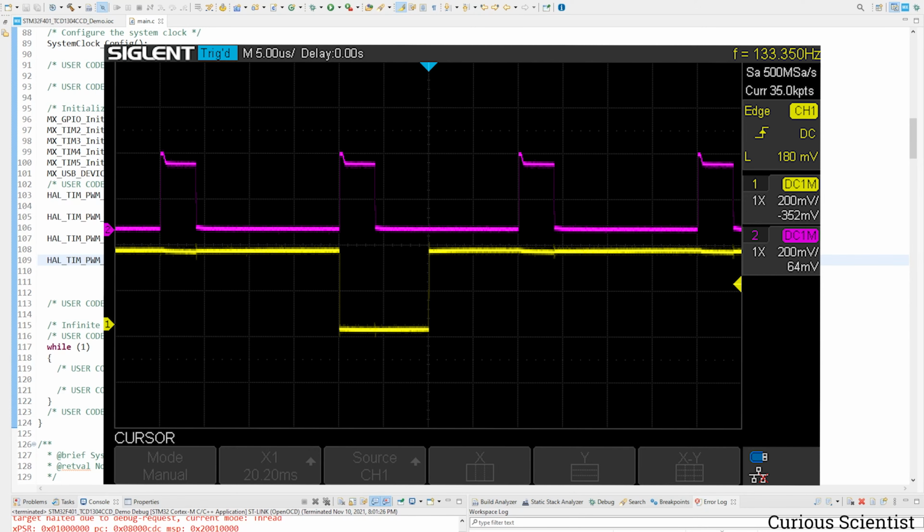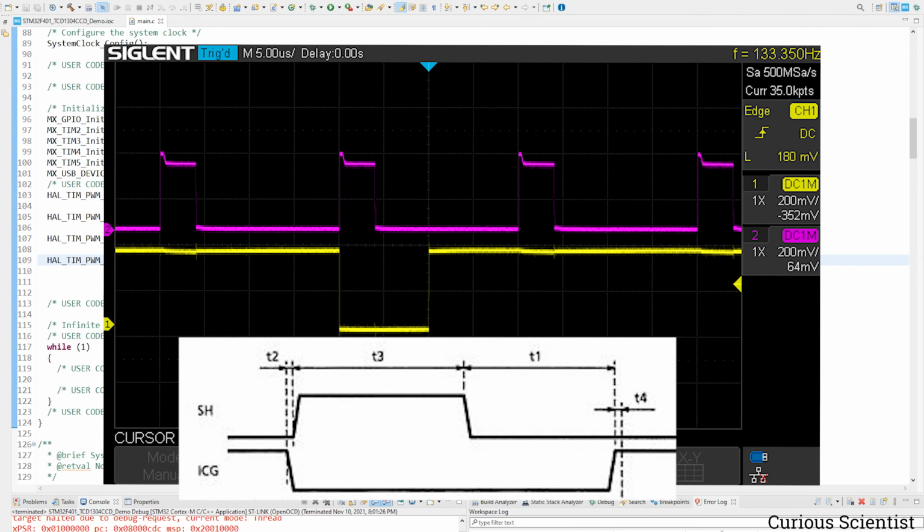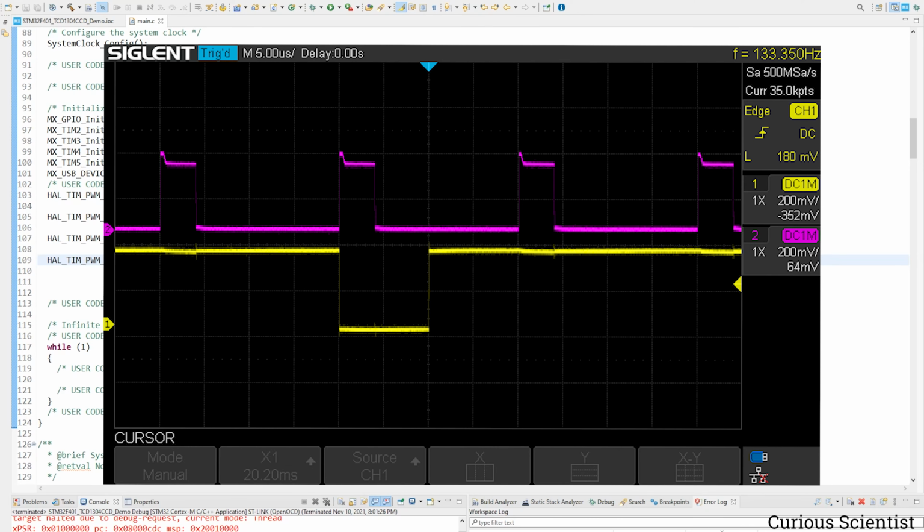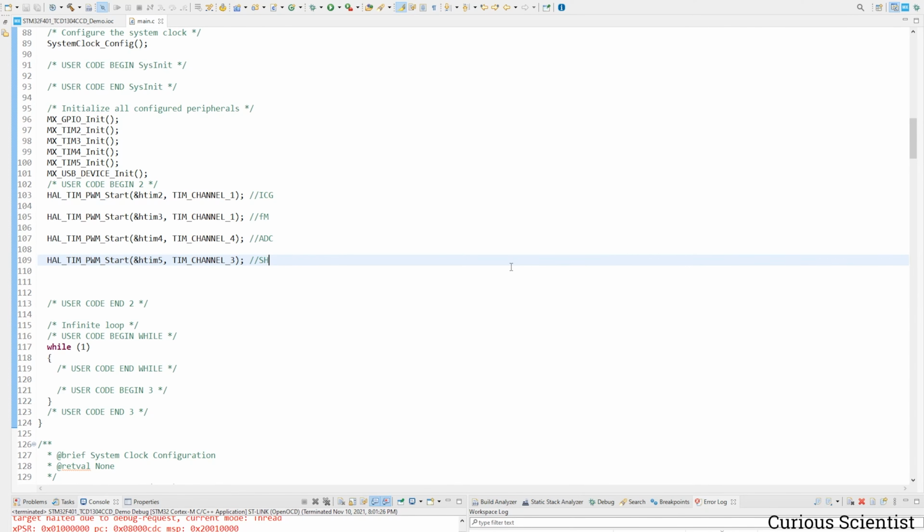And I haven't mentioned it, but the polarity should also be fixed. It's fixed on this picture, of course, but on this picture it is according to the same polarity as it is shown in the datasheet. But if you use the hex inverter as it is suggested by the datasheet, actually you should invert the polarity of these two signals, because they will be inverted by the hex inverter. So keep this in mind.